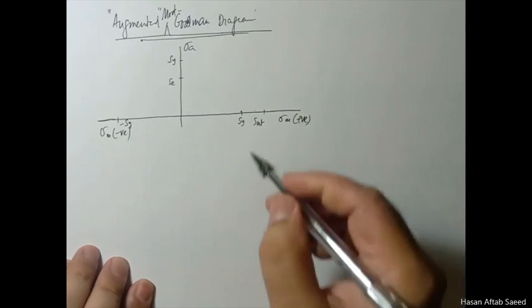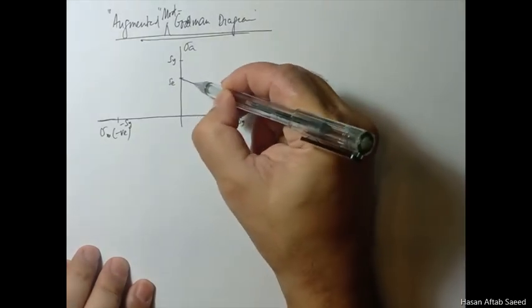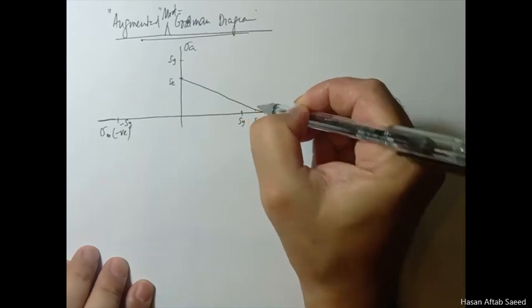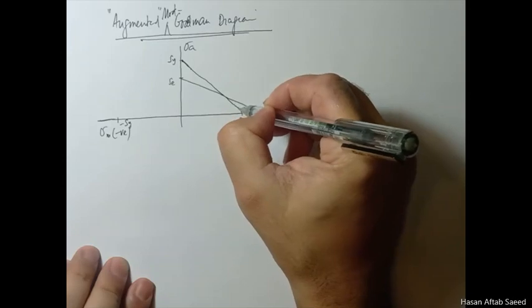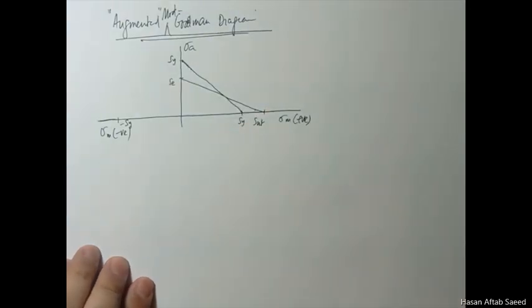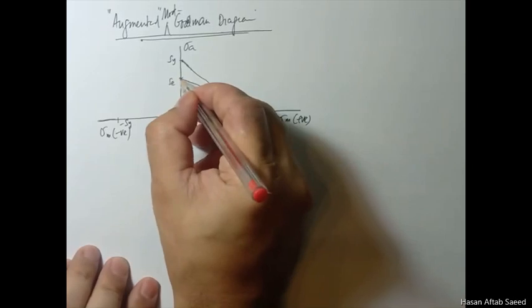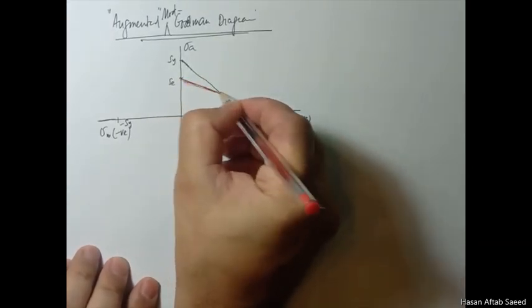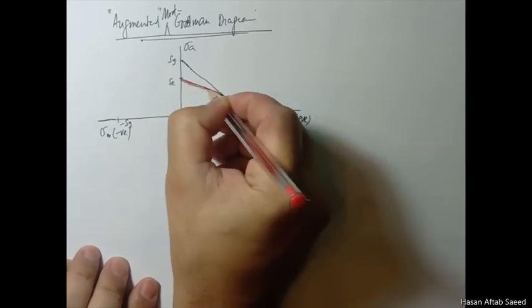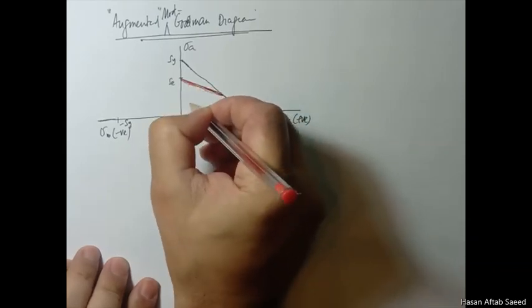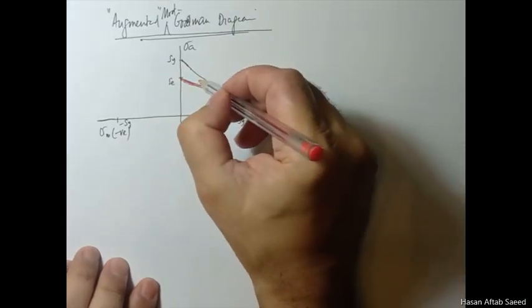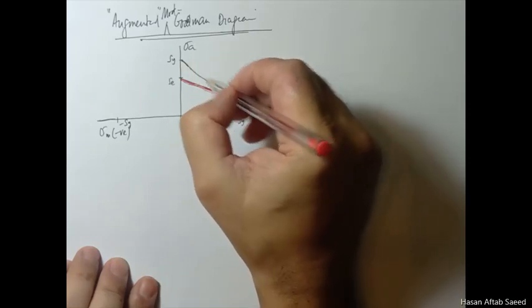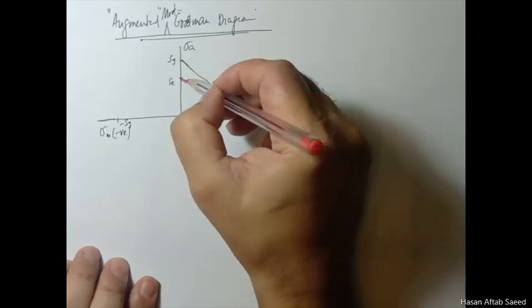So we have already seen that we joined this line, the modified Goodman line, to this. This is the Langer line. This is just a repetition of what we have done, so I'll use the same color scheme. Red for fatigue. This is irrelevant. Fatigue will occur first, so it will govern. If your point spills into this region, then already the fatigue has caused it to have life less than 10⁶. So there's no question of yielding or no yielding. So you already failed it here.